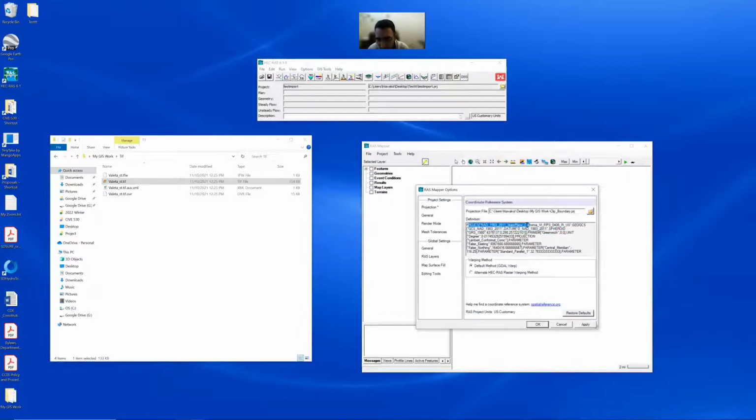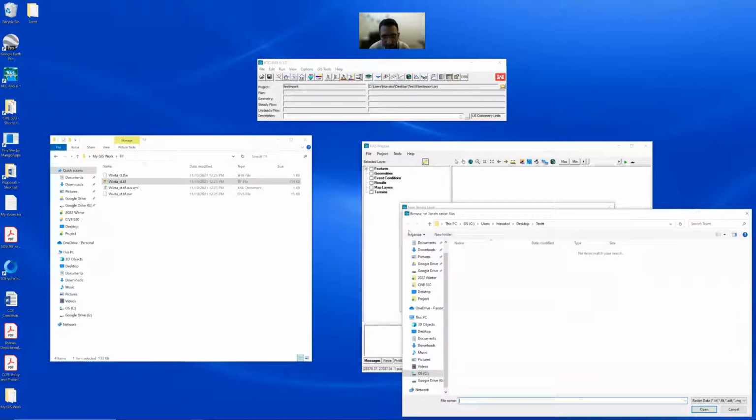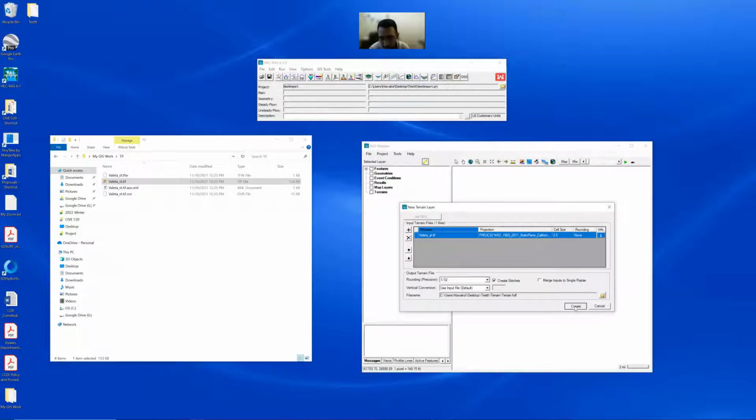You need to be able to see this stuff. State Plane, California 6. That's your projection showing you the boundaries, left and right, up and down, standard, and everything you need for that. If you don't see something like this, then your model is messed up. Be very careful about it. So you click OK, and then now you can import the actual TIFF file. So this plus button, you don't have it in this test folder, you have it in the GIS folder and then TIFF, and that's the one that you can see. So open it and create.